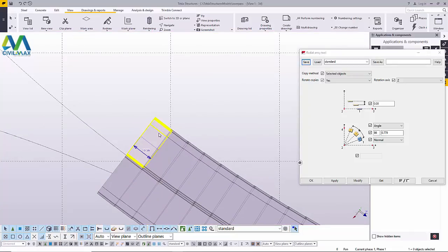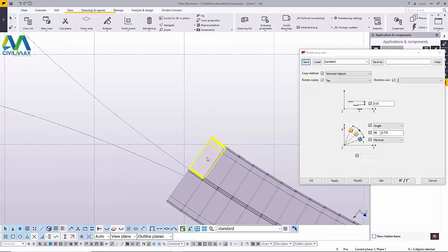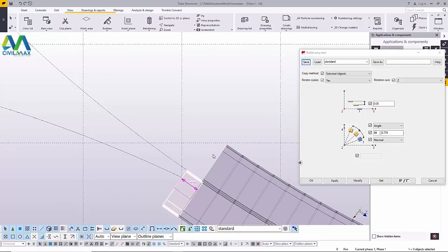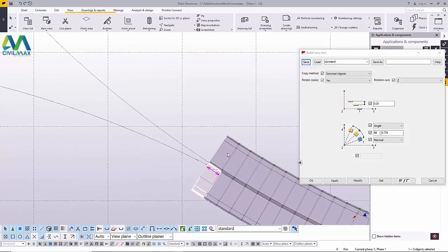We'll delete this. We have to delete that and delete that, delete that, delete this, delete everything right there till you get to a tangential point, which is where we'll start. That is where we'll use the array tool to populate that component along the path we've just defined.